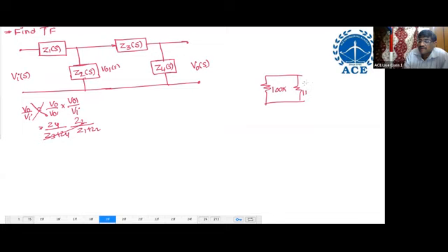Then what happened? The next stage impedance falls on the before stage. Then if you observe here, the resistance is not 100K. It will be below 1K, you will get a parallel combination. This is called loading effect. Next stage impedance falls on the before stages.